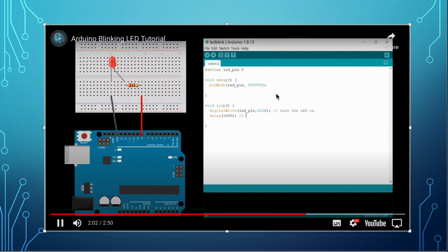the first one defines that pin number 8. Here the definition is given, so the name of the pin is an output pin. These are input output pins. We talked about this before in lectures, to understand what is what. So here it is defined as an output. Then of course this is going to be a digital signal.